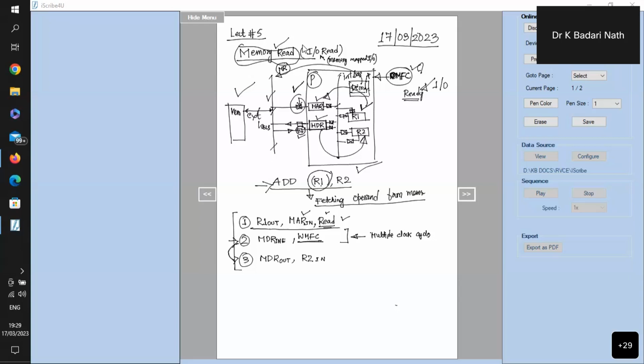So we will write a small timing diagram for this, which gives more clarity on how timing diagrams can be written for read and write operations. I will write the timing diagram with the clock cycles to start with. Let's say all the clock cycles are edge triggered, positive edge triggered. 1 clock cycle for placing the address. Let's assume I require around 3 clock cycles for reading from memory. 1 clock cycle I require for writing into the destination register. So I will separate them, 2 and then the 3, like this.